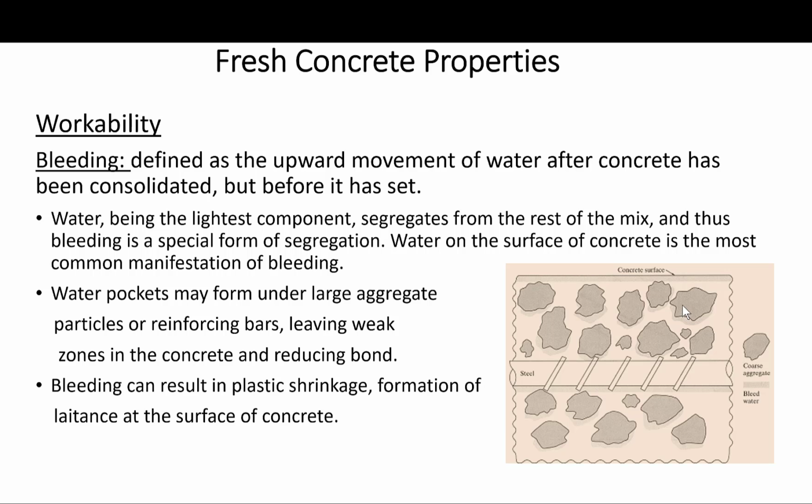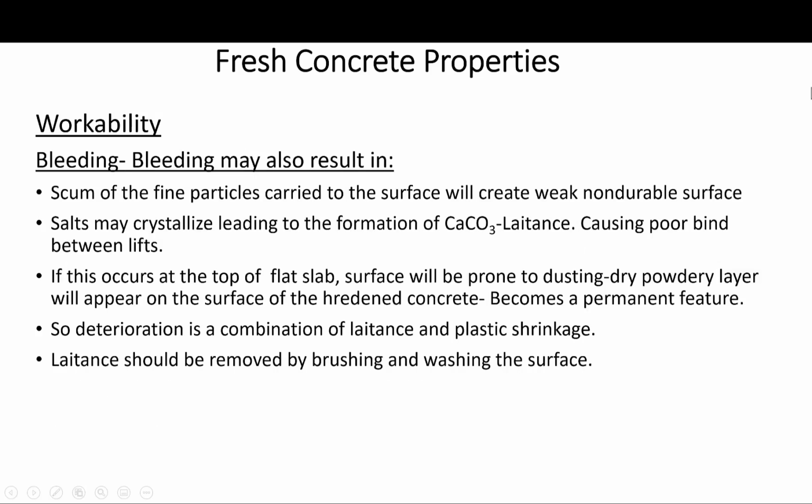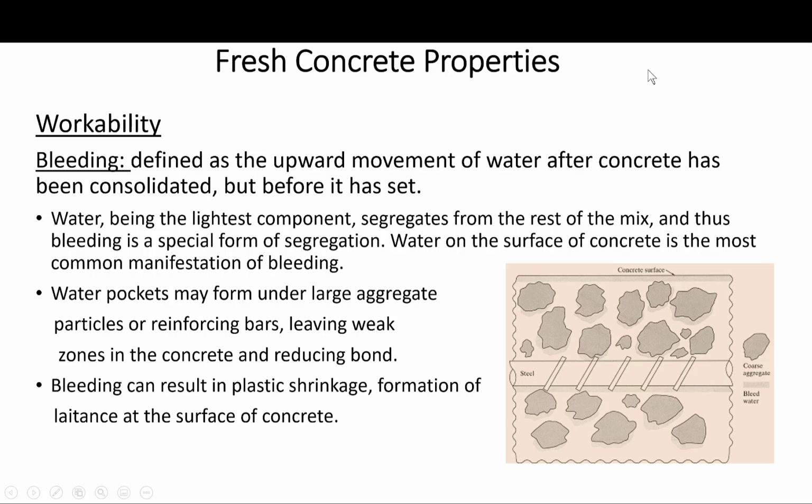Also, water pockets may form under large aggregate particles. Okay, let me go back here. I don't know if you can see it here under the aggregate particles, like you see the shadow. And also under the reinforcing bars, basically leaving weak zones in the concrete under these particles and under the reinforcing bars.